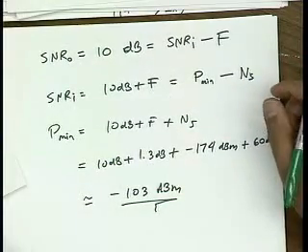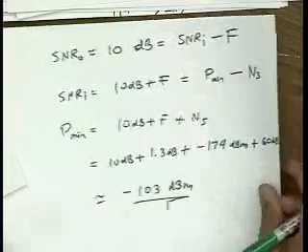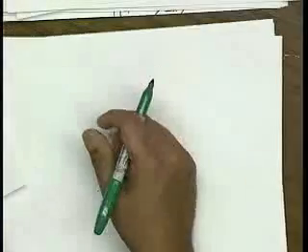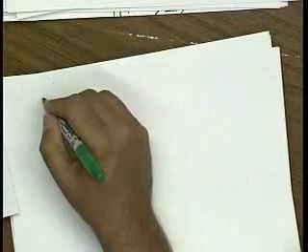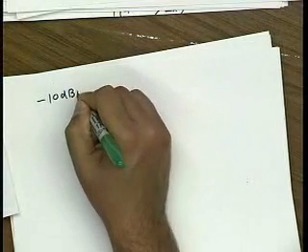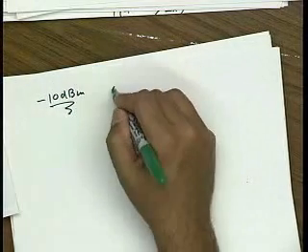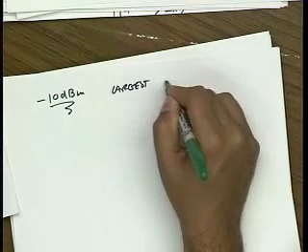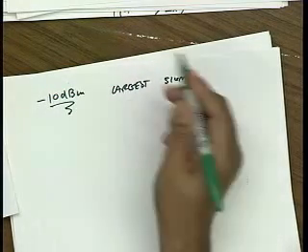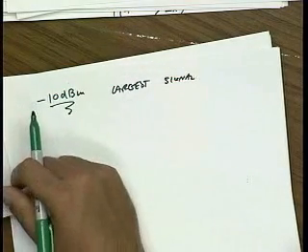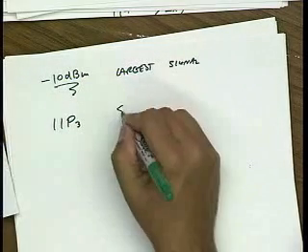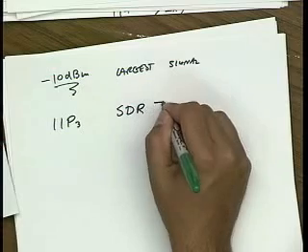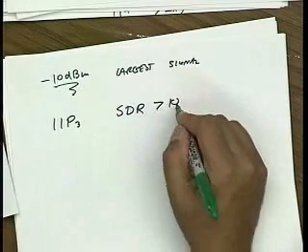Okay, all right, let's wrap it up with the last part. The last problem says we want to work with a signal as large as minus 10 dBm. So this is the largest signal, as opposed to the smallest signal that we did in the last part. So what's the IIP3 in order to maintain a signal to distortion ratio bigger than 10?